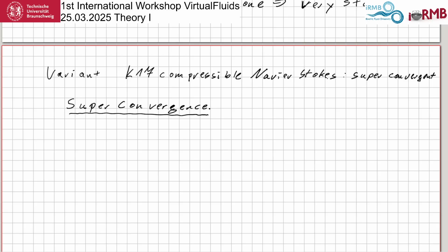This is called compressible in order to distinguish it from incompressible, where in the Lattice-Boltzmann world, and this is not how you actually should name it, there is the concept of distinguishing the variable density version of the equilibrium from a constant density version, both of which are as compressible as the other.